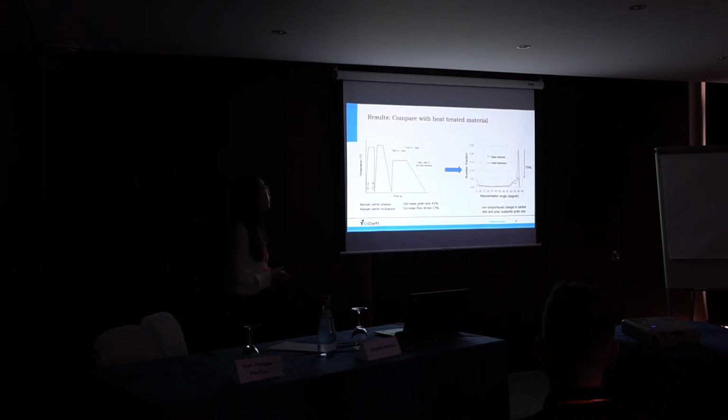Those parametric studies assume there is no correlation in the microstructures, and that the grain boundaries are the prior austenite grain boundaries. However, from the very beginning of the presentation, I showed there is a hierarchical substructure of the high-strength steels. For the real material where we performed such heat treatment to decrease the grain size, we found there is also a change of the misorientation angle of the boundaries.